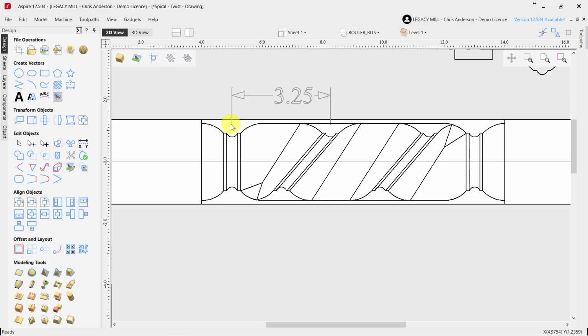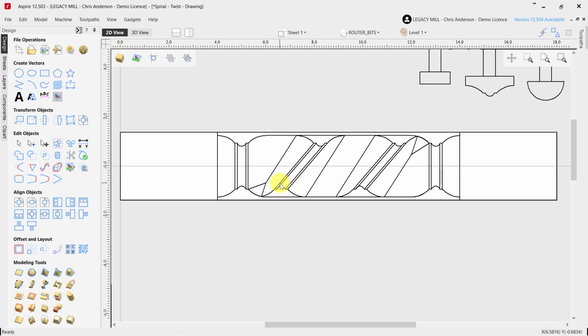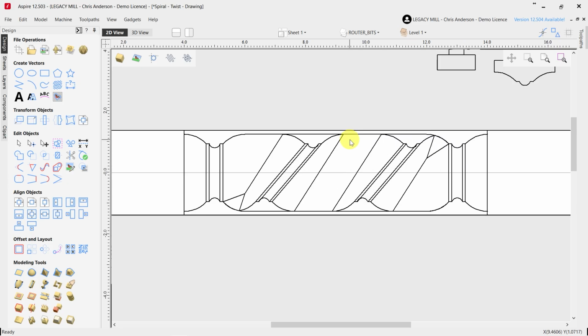And so that is the pitch that the cutter would have, the distance it travels per rotation as it went down that entire spiral. And you'll notice that it leaves sections between the spiral that are untouched, that are simply turned round in those areas. And that could be a design that someone wants. By just controlling the pitch and the number of starts, we can create other unique shapes and designs other than having cutters be back to back to back with our spiral twists.